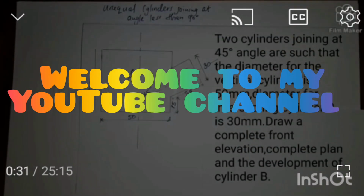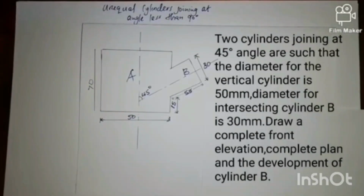Elevation, draw the plan, draw the development of the cylinder that intersects the vertical one, the cylinder B. So that's what we are going to draw. And now for the start, what we shall do is to draw the given front, and then we complete it. Then we shall draw the plan, and then we complete with the development.